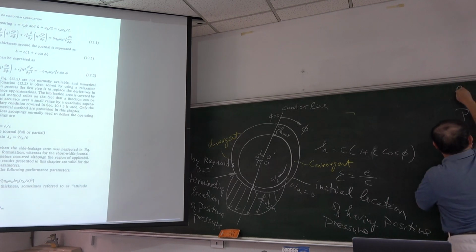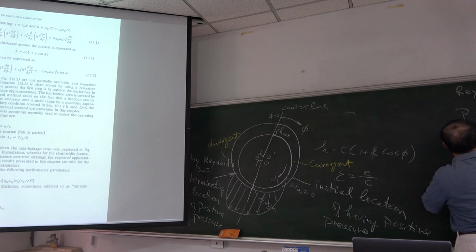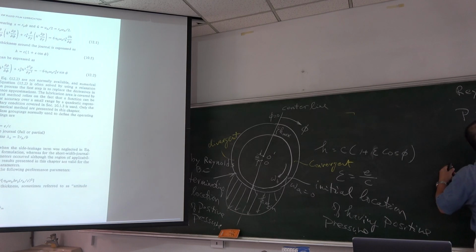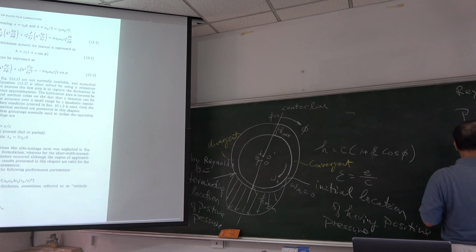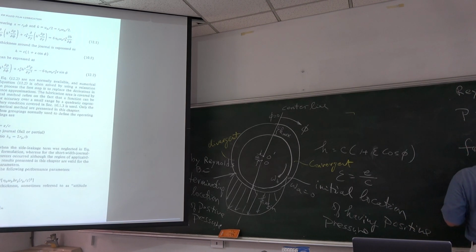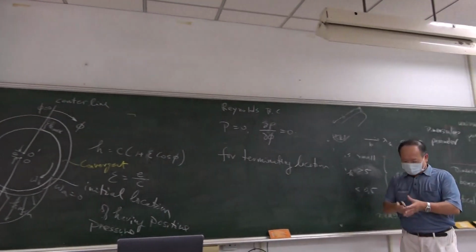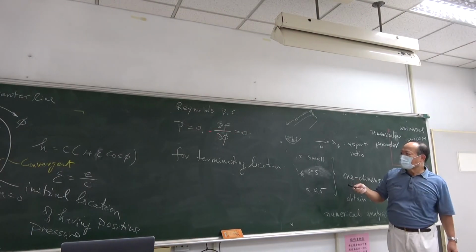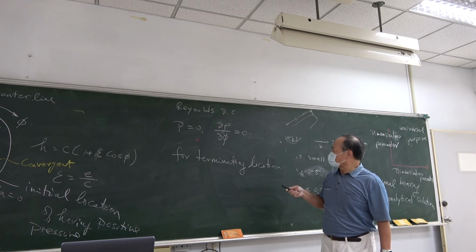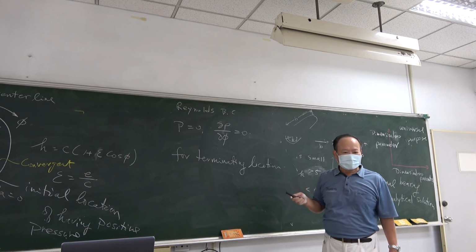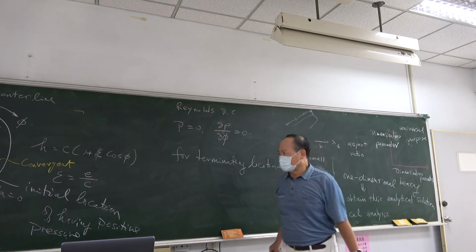That's called the Reynolds boundary condition. If your pressure reaches these two boundary conditions, there is cavitation.